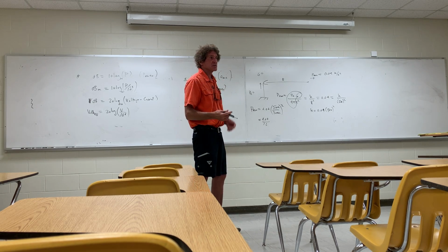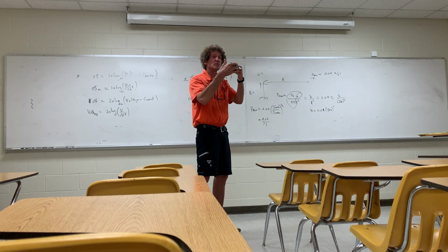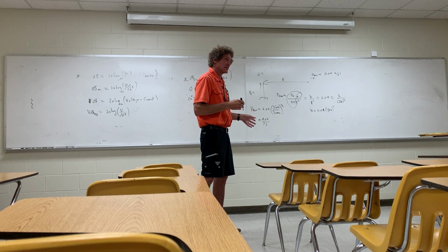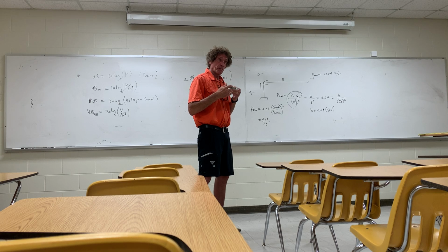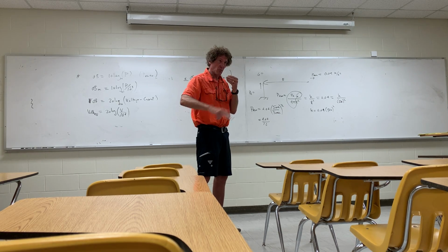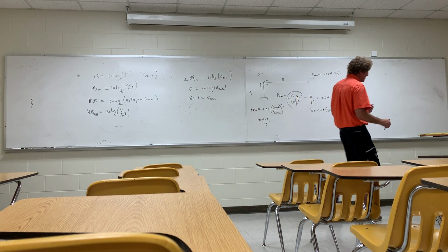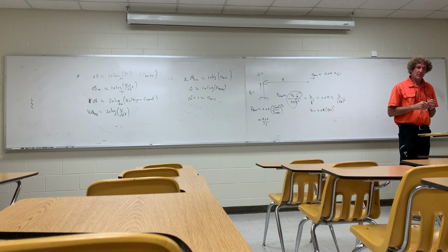The real thing about this is power density falls off proportional to 1 over r squared. That's one of the things you should at least appreciate about this. With radar though, the power return is proportional to 1 over r to the 4th. It really falls down quick, all right? Radars, you don't get much back for the amount you send, almost none.